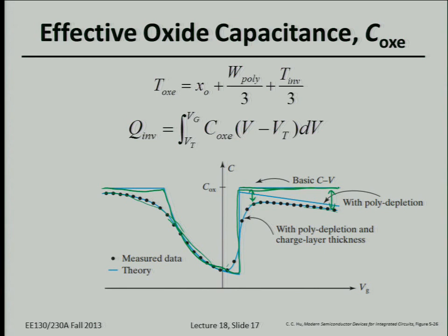Yes, Louis? What is the slope? It would depend on the ratio of your real oxide thickness and the gate depletion width. You can actually calculate this. But for this class, just understand qualitatively why in reality we never see the true oxide capacitance for a small signal measurement of an MOS capacitor. It's due to two things, but only one of those depends so strongly on gate depletion.